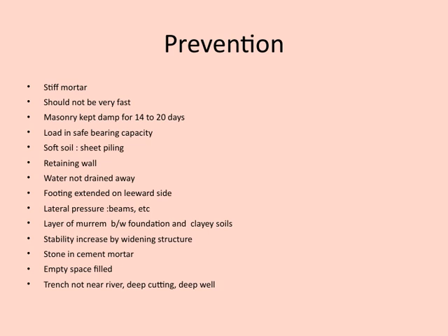When constructing with stone and cement mortar, filling any empty spaces prevents weak points. And finally, when excavating, avoid trenches near rivers, as deep cutting or deep wells can destabilize the ground and cause unforeseen problems. All these measures are interconnected and contribute to a comprehensive approach to preventing structural failures and ensuring long-term stability.